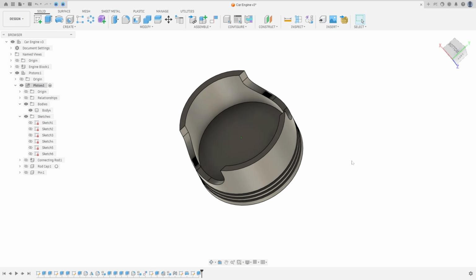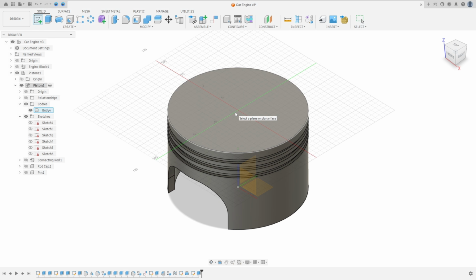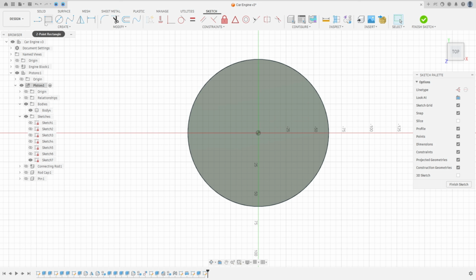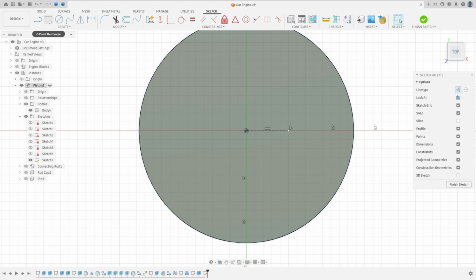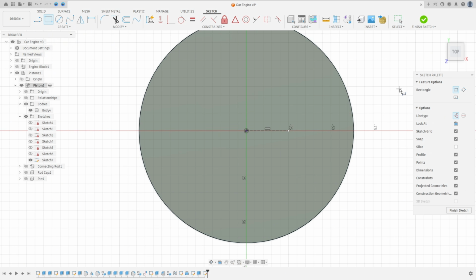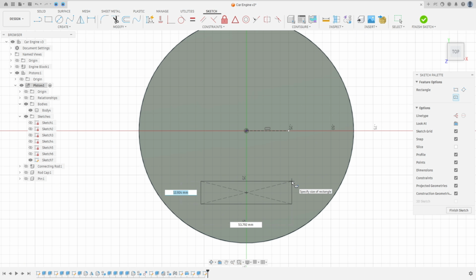We made this one. And now go to create a sketch and select the top face, and select a line, a construction line here. Make a construction line. And here select the 2-point rectangle, center rectangle. Make a rectangle here. Remove the construction geometry. And this rectangle has 19 millimeters by 50.8 millimeters.